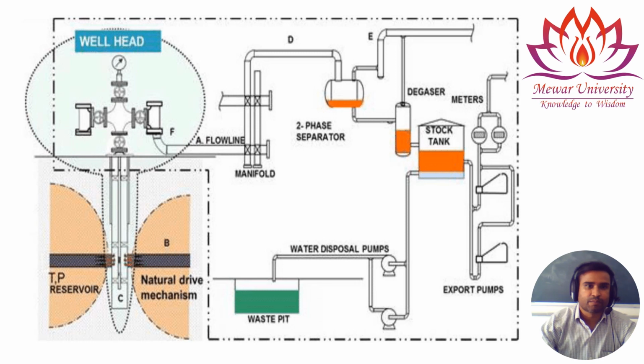Then further it is sent to the degasser. The gas that is dissolved into the oil is separated from the oil in the degasser. Then further the oil is stored into the stock tanks and it is exported through the pump.